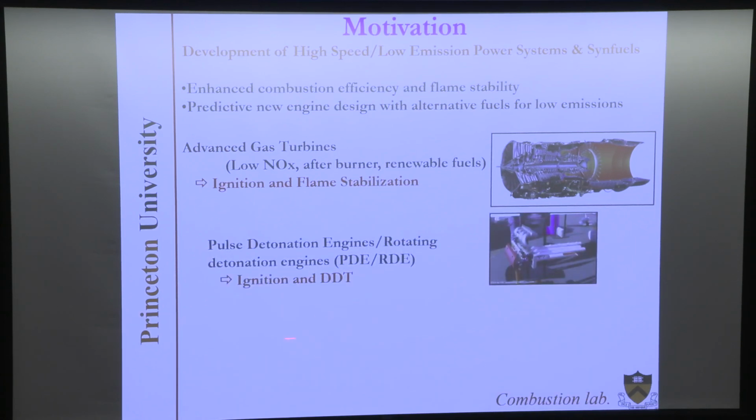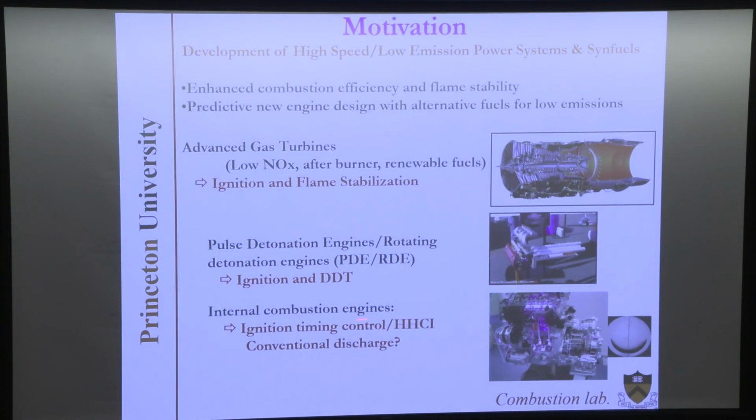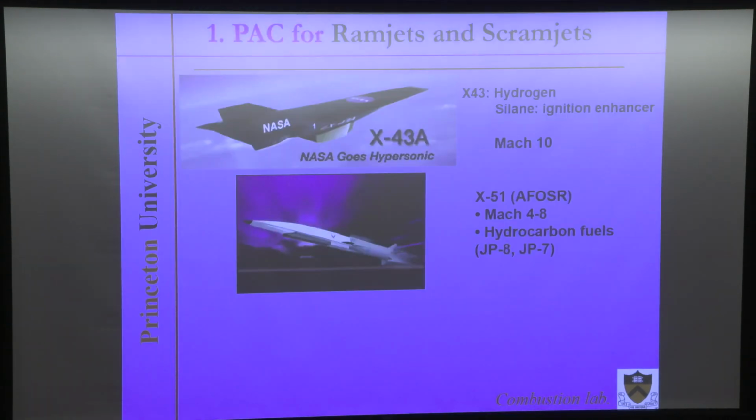Also, detonation, rotating detonation or pulse detonation become interesting, but it's very hard to control the detonation in not fully mixed mixtures, and they often have instability. In internal combustion engines, how do you control an HCCI? How do you enable low temperature combustion so that it can reduce the heat losses? So these all provide opportunities for plasma to do something.